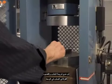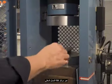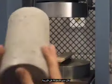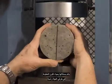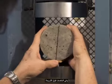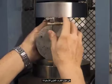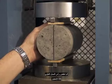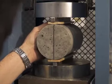Next, center one wooden strip and stiff steel bar along the center of the lower bearing block of the testing machine. Now place the cylinder on the strip and align so that the lines marked on the ends of the specimen are vertical and centered over the strip. Next, place the second wooden strip and steel bar lengthwise on top of the cylinder. Then lower the upper loading head of the testing machine until the assembly is secured in the machine.